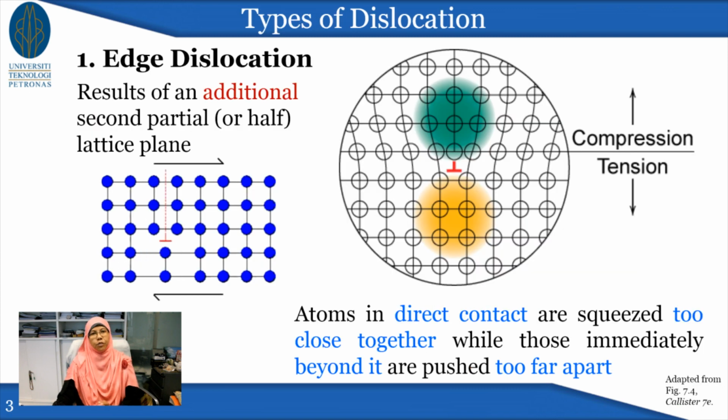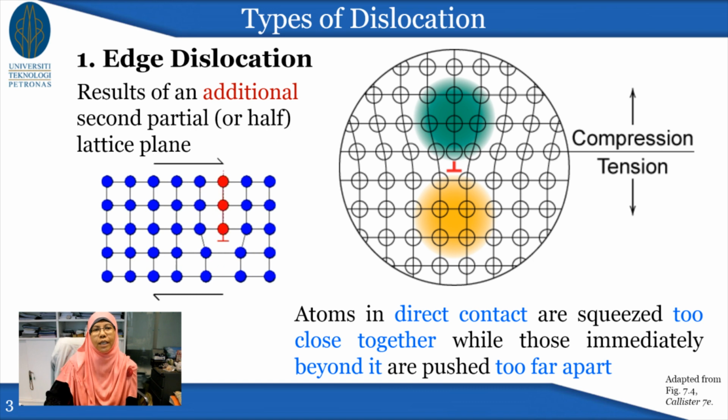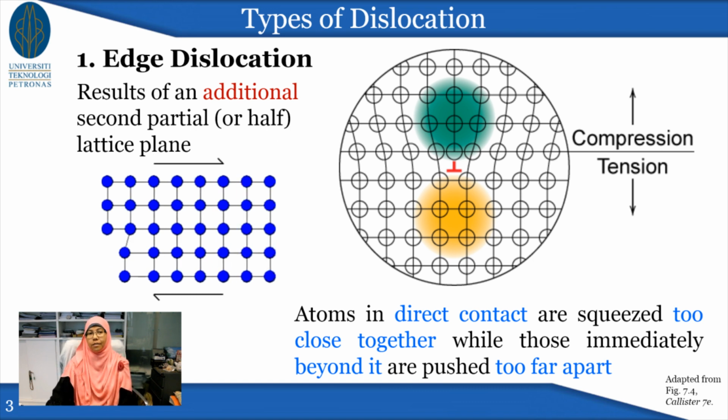How many types of dislocations are there? So basically what we learned, there are two types of dislocations. One is what we call edge dislocation. It's shown on the left side here, right, where you have the movement. If you can see here, the extra half plane indicated by the red line in the video here, that extra half plane is what we call edge dislocation, and it seems that it's moving from right to left in that picture, in that schematic, right?